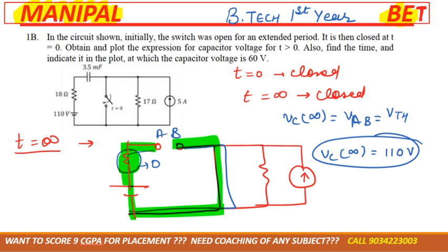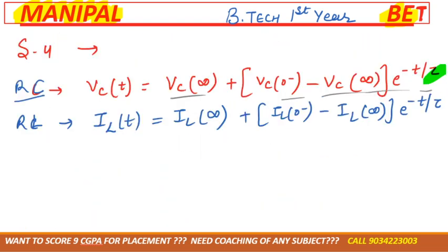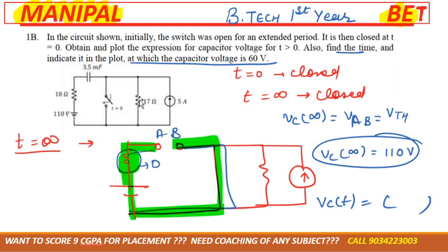Okay? So before that, where have they given the transient? Once you get the value for RTH, you'll get the equation form, and they said find the time. So this is the equation. Now they have given VC of t, all values you know. Can you get the time? Tell me. Calculate the infinite value, then calculate the time. What they have asked, I told you, whatever they ask, calculate that thing.